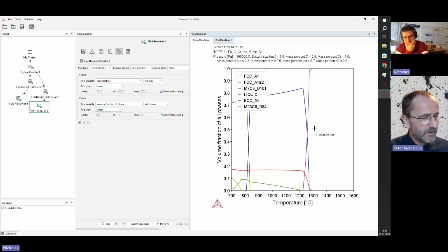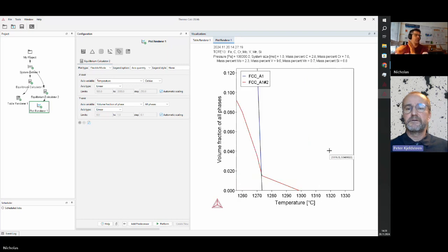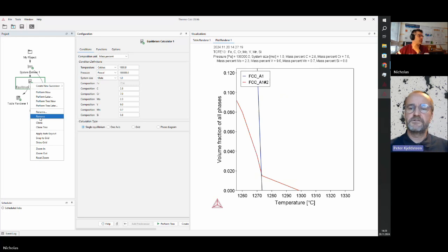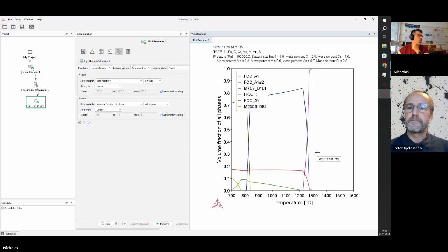Now comes the story. When we made this alloy, we were atomizing it, and we had difficulties: the alloy clogged in the nozzle. When I opened up the nozzle and made a microstructure analysis, I could see a lot of primary carbides, a lot of MC carbides. The vanadium carbide, as you see, has this arm into the melting phase. When I cut through one of these carbides and measured the chemical composition in SEM EDAX, I could see a substantial amount of nitrogen at the nucleation site inside the carbides.